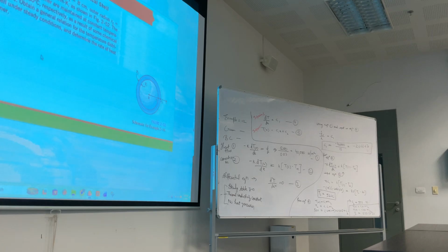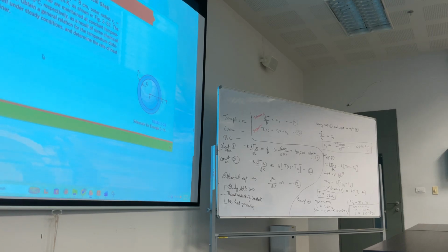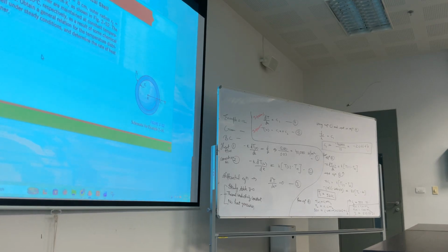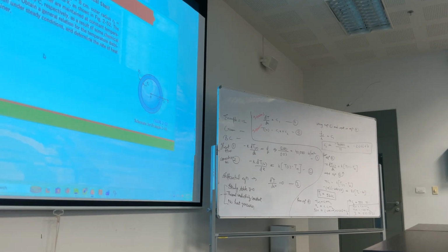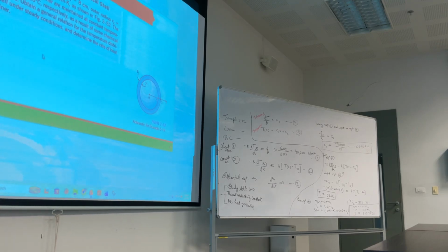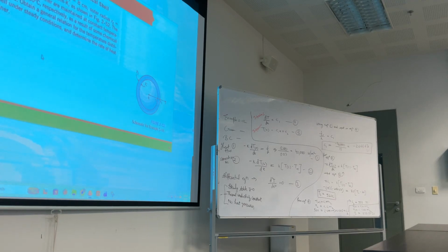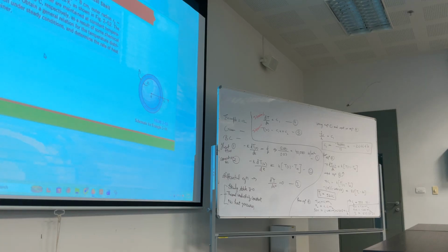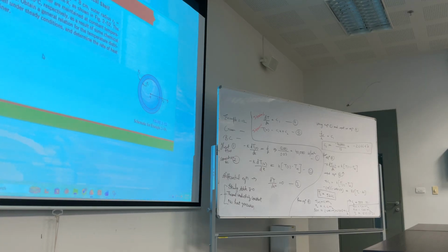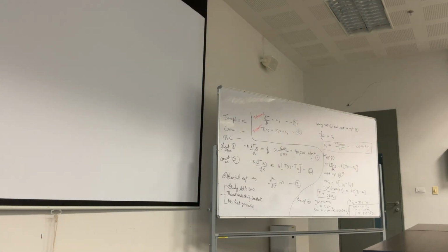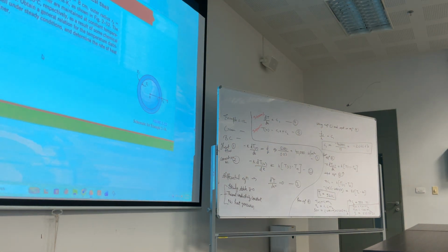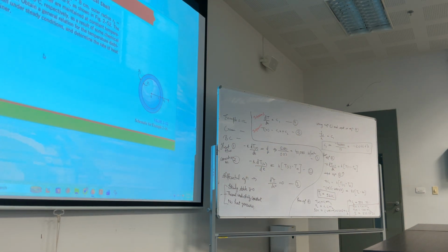In this question, it's a sphere. They have written in the question that it's a sphere, so you will use the differential equation for sphere, not for plane wall, right? Consider a spherical container of inner radius R1 and outer radius R2. Thermal conductivity is given. Is thermal conductivity constant or variable in this case? Constant, right? Because it's given.